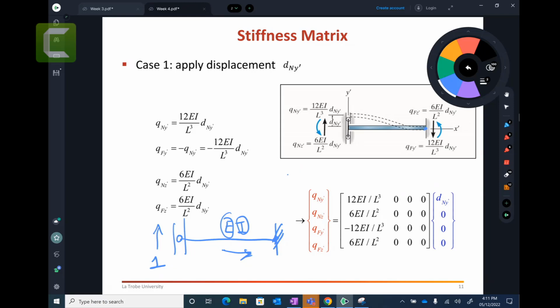So that is the measurement of a geometric property. You can make it in a shape that will have a very high I value, meaning you can't bend it. If it is a small I value, you can easily bend it. That's how the I value, the moment of inertia, is measured. This is a geometric property and E is the material property. So I hope you understand the story.